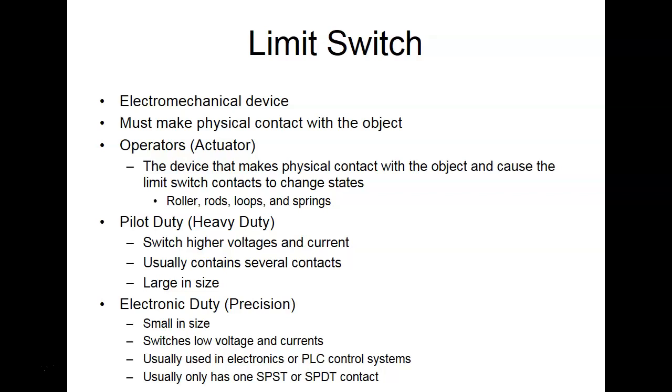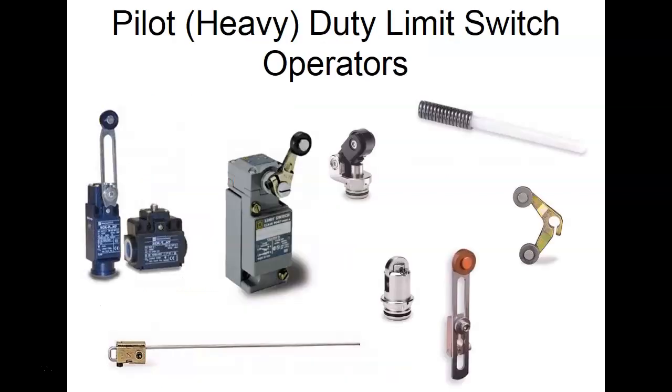So electronic duty, we can use those to control loads, but they're going to have to be very low voltage and very low current. The majority of the time, these are the ones used in PLC systems where they input into a computer instead of a load. So these are some heavy duty limit switches, and these are some of the operators that we might run into.